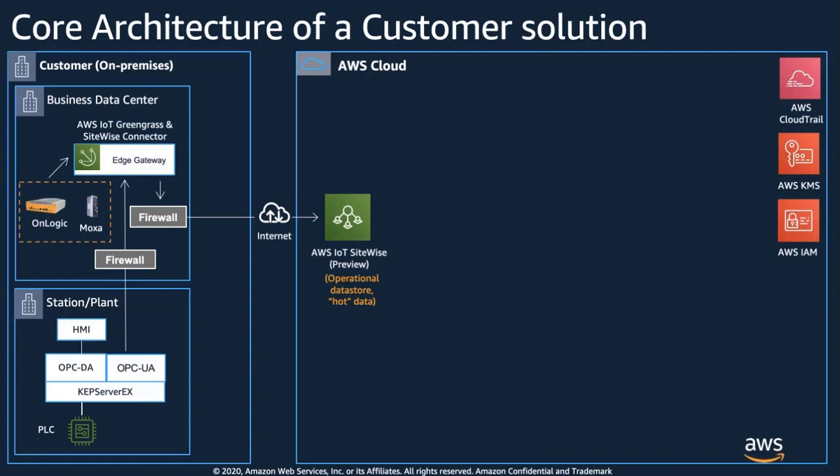And then once your data is in IoT SiteWise, you do asset modeling within SiteWise. You create virtual assets or virtual representations of your assets and processes in there. SiteWise provides an out-of-the-box managed web application for you to monitor the asset hierarchy you have created using your asset model. That's used by personas like operators, managers, and analysts who are monitoring your operations on the floor.